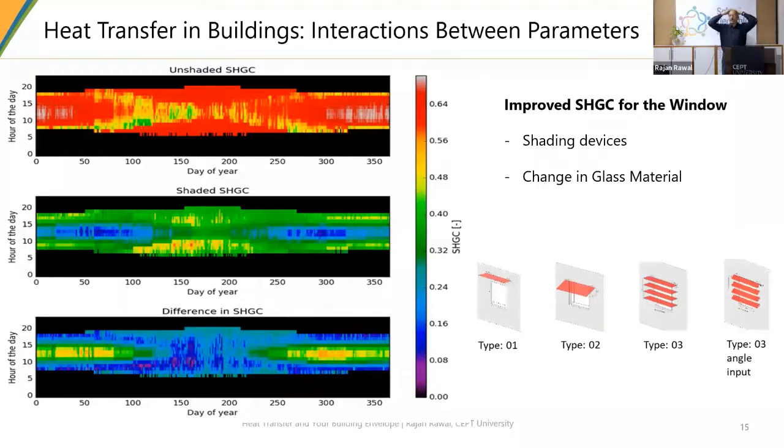It's more on your head. So a little bit of shading on your building will cast a long shadow on the vertical surface, and that is how the solar heat gain is improved during the summertime when your altitude of sun is very high. So this is one example of how you can do the analysis for your overhangs.